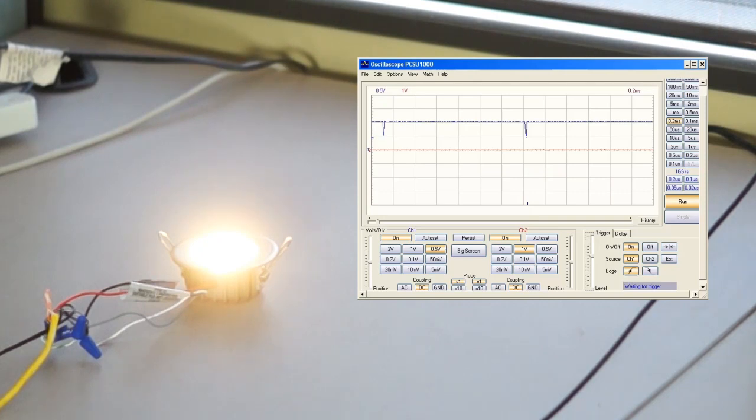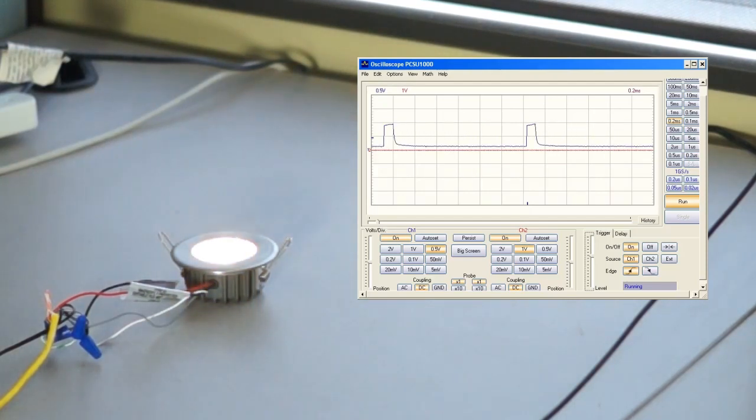We have the oscilloscope now attached to the output of our PWM dimmer. We will now initiate a slow fade off. Notice that as the percentage of time that the voltage is applied decreases, the light grows dimmer. Remember that this is non-standard, and we've selected in software the inverse option.